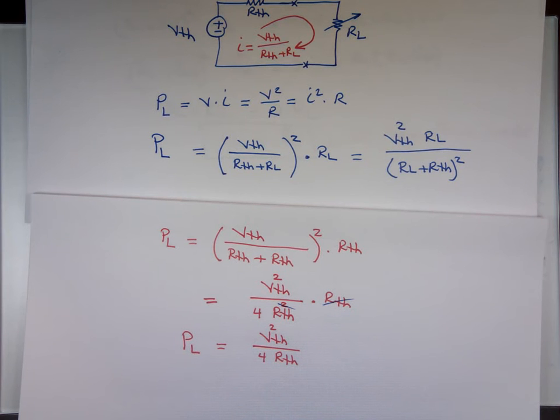Should we just remember that? You should remember, for maximum power transfer, R thevenin equals R load. That's the key. The rest you can derive. You'll use that a lot, so you'll know it actually. You won't have a choice with memorizing it because we use it all the time. But if you remember that one, then you can derive the rest of it. These guys are equal, that's 2R thevenin, you can find the current.